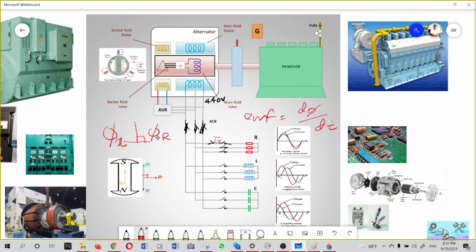As this newly induced magnetic field interacts with the magnetic field on the rotor and causes the retarding torque, then as the speed drops, the governor will sense that speed drop and increase the amount of fuel to bring the generator back to normal speed and to restore EMF.